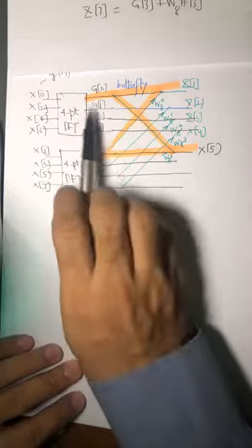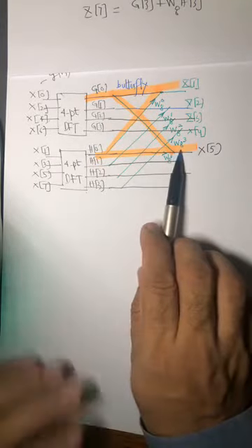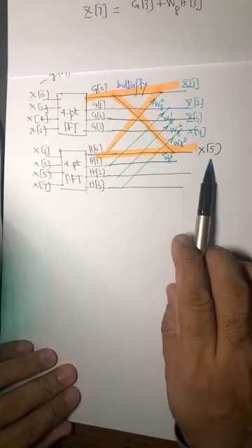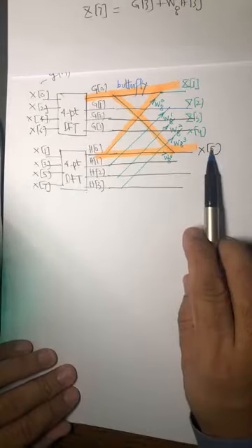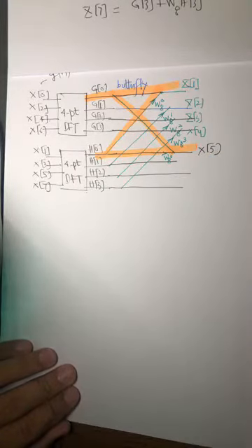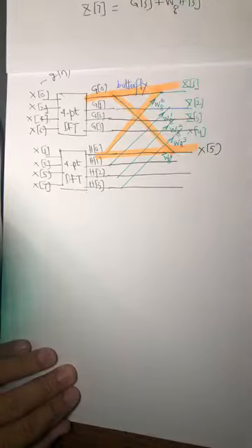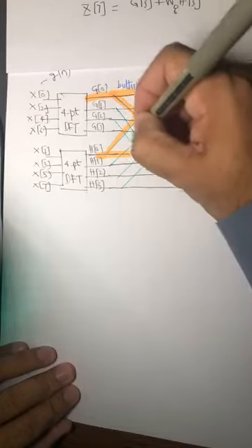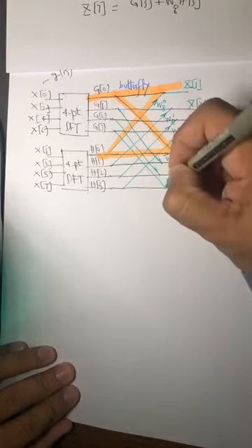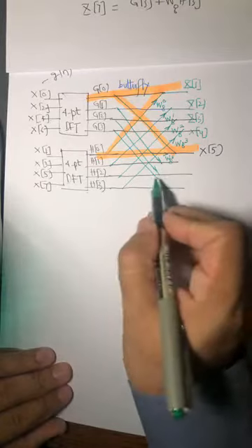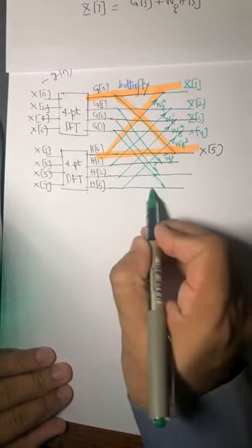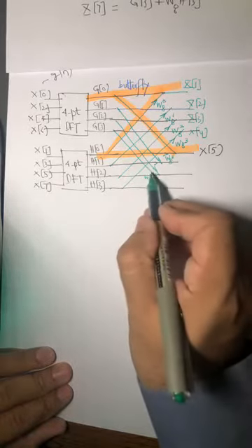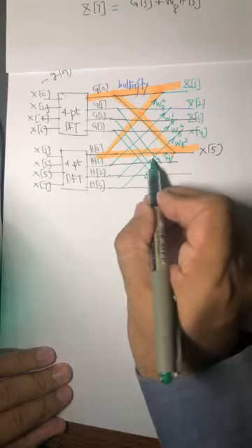Okay, so you have G0 and H0 used twice, and you also see the saving to calculate 2 of the points of the final DFT. Okay, and similarly here, once you bring this down, bring this down, and bring this down, and bring this down. And here you have to multiply it with a twiddle factor, which is W8^7, W8^6, and W8^5.